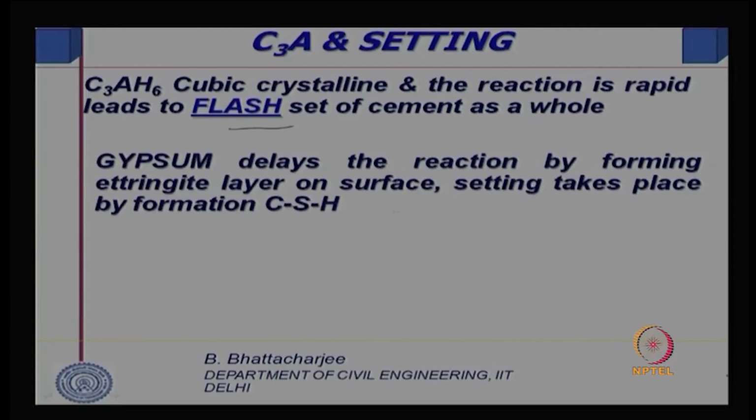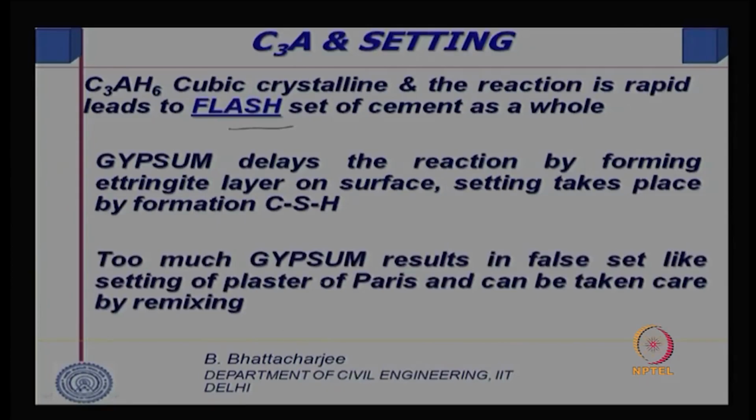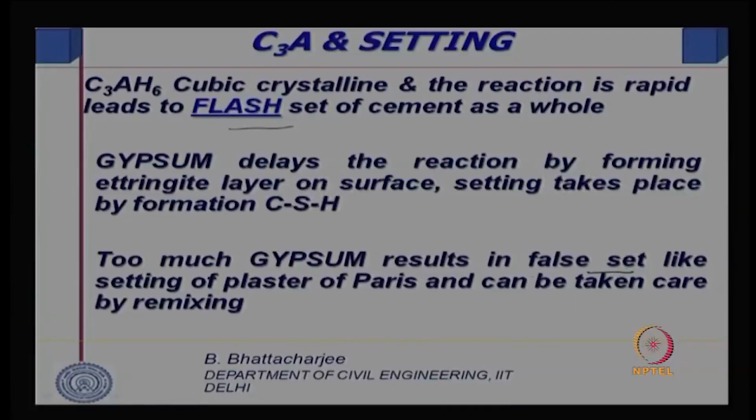We will look into this in more detail from time to time, and setting takes place by formation of CSH. Too much gypsum is also not good, because it results in what is known as false set, which sets like plaster of Paris, because gypsum itself will react with water and form hydrated gypsum, like plaster of Paris, and therefore this is also not desirable. This is called false set, but you can actually remix it a little bit and it will set again.